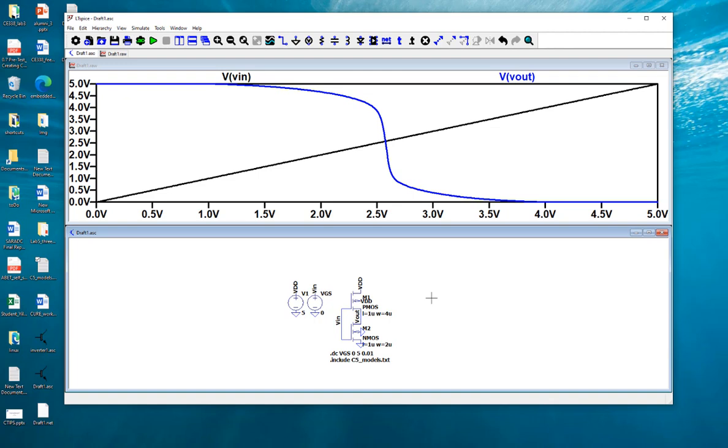So eventually, PMOS is not, I don't want to say it's stronger. It's just they are pretty much the same strength over here right now. We just need a wider PMOS because the mobility of the holes are less than the mobility of the electrons. That is why. So you can modify the width in order to reach that desired switching point for the NMOS.